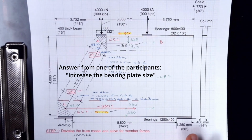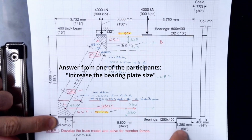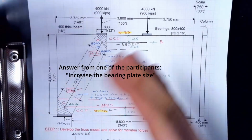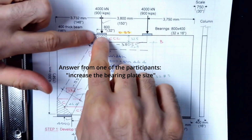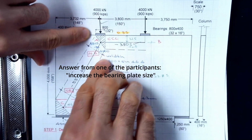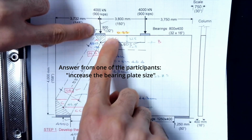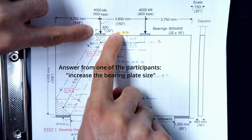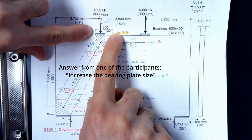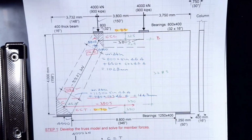Absolutely, yeah. I think that's the easier solution, because as you can see, this larger bearing passed. The issue is the bearing plate size. When you check the bearing plate, it passes, so there is no crushing under the bearing plate, but because it's really concentrating the strut at a narrow distance, increasing the bearing plate is a very easy solution. Definitely, you can do that. You can solve it by increasing the bearing plate dimension. That's my solution. That's how I did it.